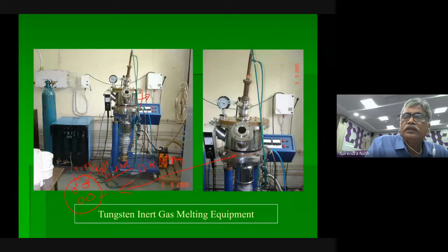Close the chamber. Then see here, there is a locking mechanism, we will tighten it. Then this is the vacuum. We will switch on the vacuum pump. This vacuum pump will suck out whatever external gas is there in the chamber. Now the entire chamber is airtight, so nothing is going inside.